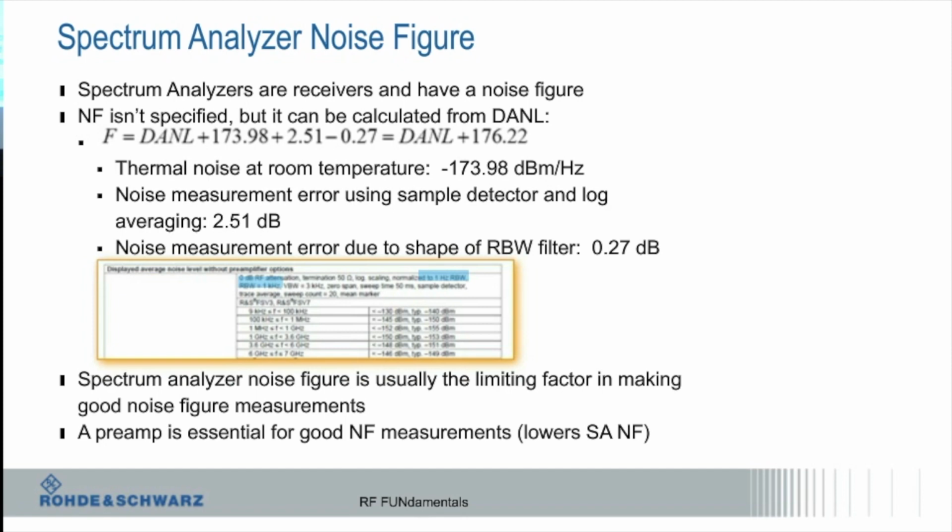Then you can reduce the bandwidth. There's a resolution bandwidth, which tells you how big a chunk I look at a time. Obviously if I look at a 1 meg chunk, as I talked about earlier, 10 log of 1 meg is 60 dB, so that sets my noise floor. I can reduce that by narrowing the IF bandwidth, but then it moves slower, because it goes ka-chunk, ka-chunk, ka-chunk in that size of piece. So that's the next thing you can do.